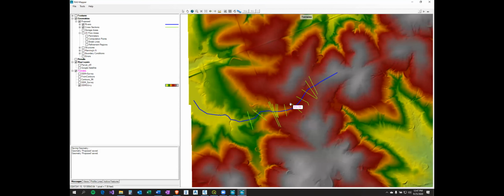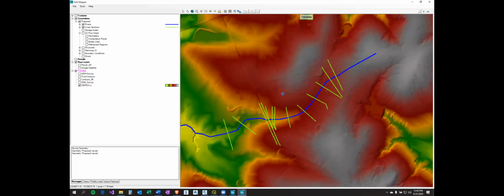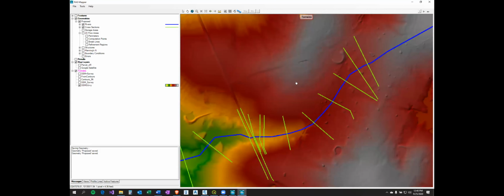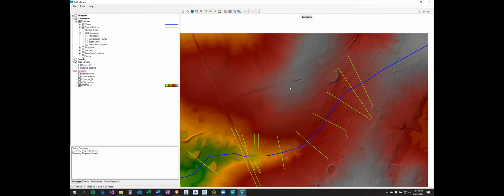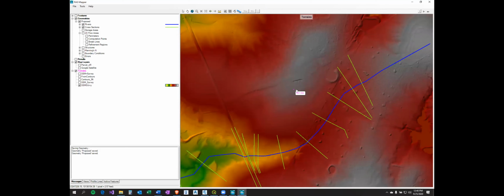I would recommend for most, especially those that aren't real familiar in ArcGIS, to go ahead and let RAS do the aggregation. It'll bring in multiple resolution DEMs, and it will stitch them and aggregate them and do the pyramid scaling kind of automatically, which is really a beautiful thing to somebody that doesn't really have a lot of experience in a GIS program. Yeah, so I was actually going to ask about that pixel size,